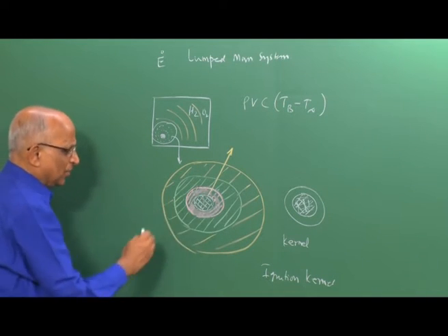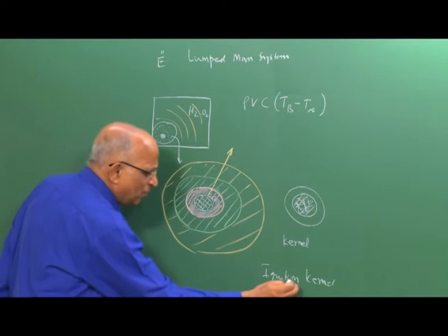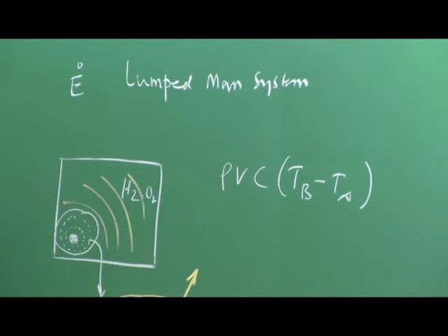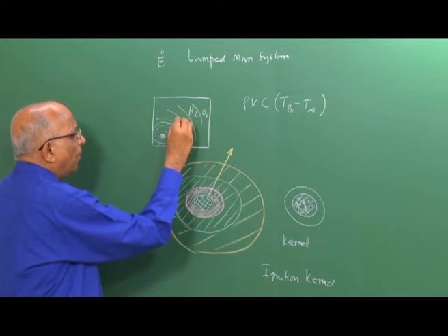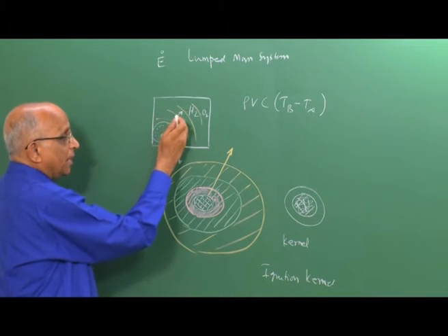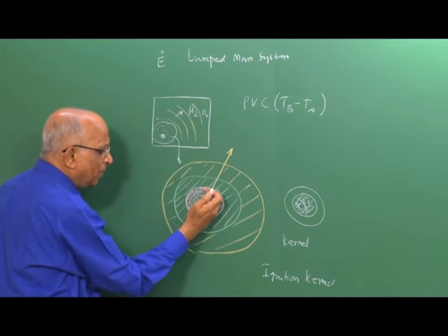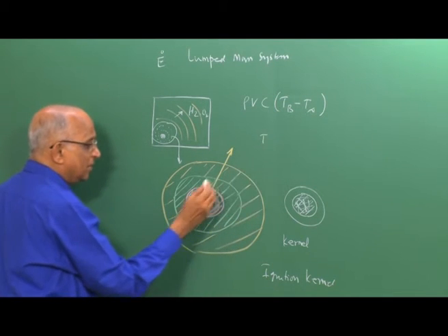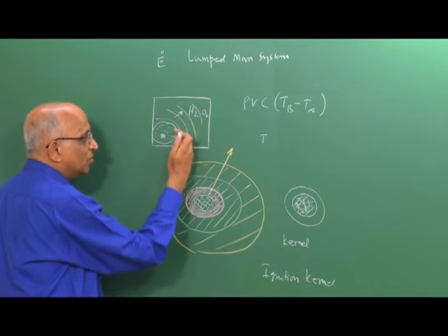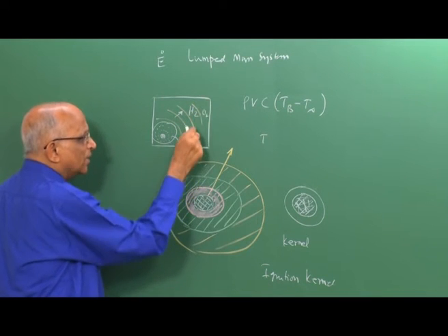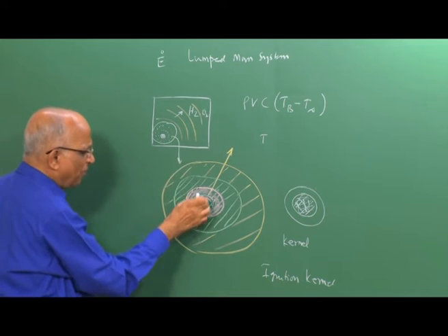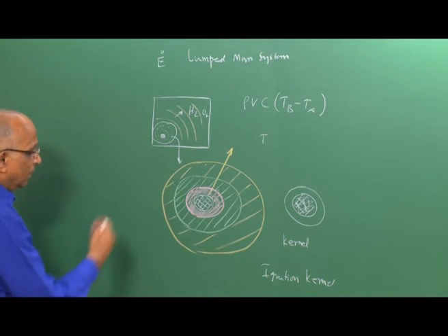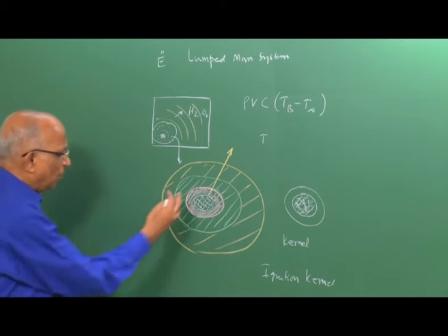But to be able to find the critical size of the ignition kernel, and therefore ignite the gases and have a flame moving out, it is necessary for us to get some idea of the rate or the speed with which the combustion wave moves. What do you mean by combustion wave? It is a zone of reacting gases, where the temperature increases. So the speed at which this zone moves out, the thickness of these zones, and some more definitions are needed before I can determine the ignition, and this is what I do today.